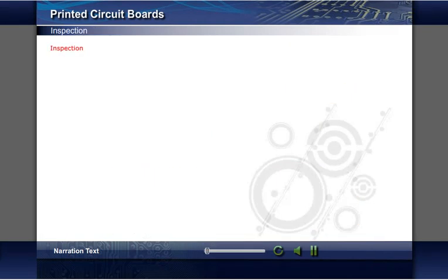After making of a PCB, it is inspected for faults. PCB is inspected for dimensional accuracy, hole diameters and pad sizes. Visual inspection is done using high-index magnifying glass. It is checked for open or short tracks and open or short pads.